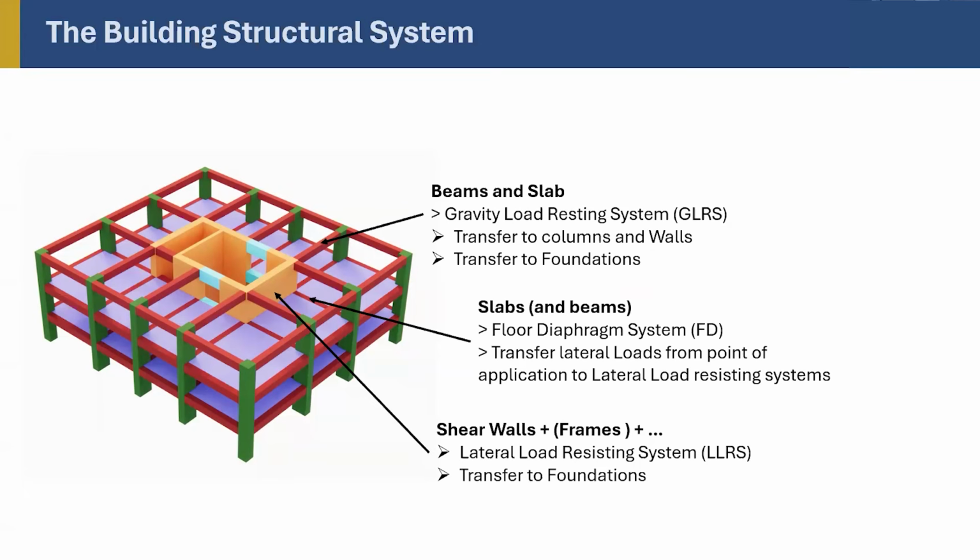The design of this floor diaphragm has not been something new, maybe 15, 20 years old. Before that, people never realized that floor has to be designed for these in-plane forces. So now the diaphragm design for in-plane forces is another step that we need to perform, especially for tall buildings in a tower where it comes down and you have a large podium. Let's say there's a tower here, and then at the ground level you have shopping malls. From that tower, this shopping mall has a very different behavior. It will try to stop the tower, distribute the load, and so on and so forth. So we'll talk about that. So the floor diaphragm becomes very important in that case.